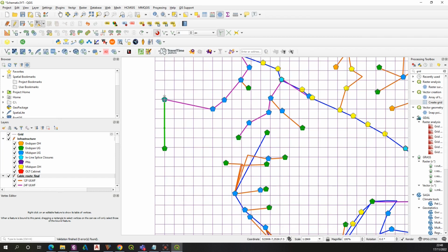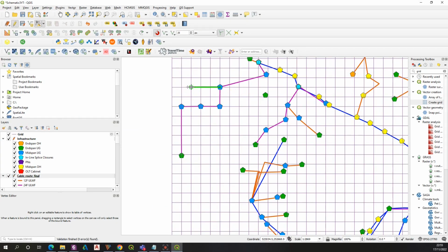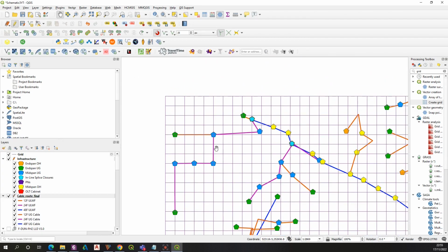Unfortunately, I use QGIS 3.12 where the mandatory step is to move the given layer at least once. Therefore, at first glance you may think that this option doesn't work, but it obviously does. As you can see, in the given section, for the first time I have to move two layers separately, but the next time I can pull them together, alright? So this is the way we can make our diagram straight, like the straight line diagram should look like.